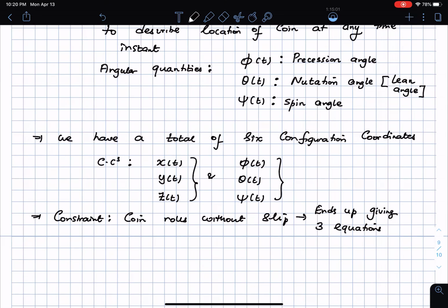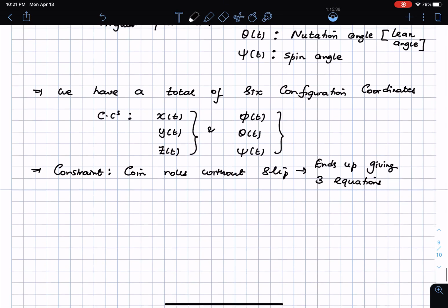Okay, which means that the system is non-holonomic, which means that we cannot come up with generalized coordinates in order to look at the equation of motion directly. So we have to make use of the configuration coordinates, and somehow we can make use of these configuration coordinates, but then categorize the writing of the Lagrangian in terms of the angles theta, phi and psi by making use of certain subtleties and relationships, and then we may actually not even need to use the multipliers in this particular problem.